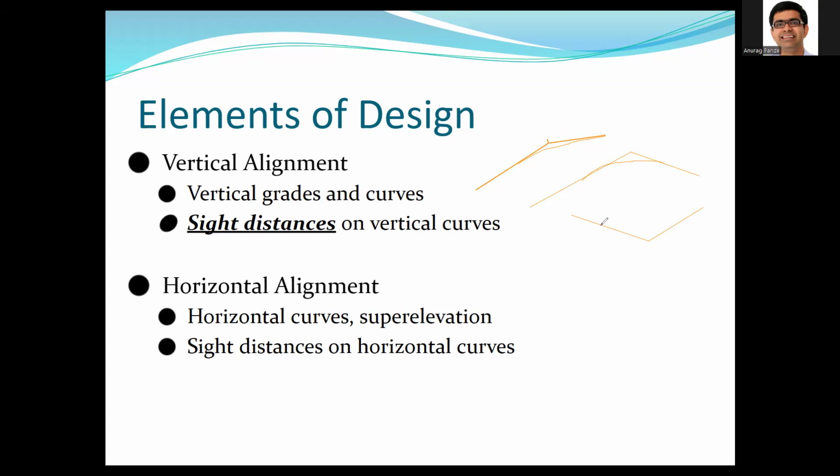Okay, and then same thing on the downgrade side. They're hard to do on a computer screen, but you're trying to do these transitions so that the change of grade from upgrade to downgrade is smooth in nature, right? So it's not discontinuous from one point of the curve to the other. Okay, and then obviously we want to make sure that adequate sight distance is available.